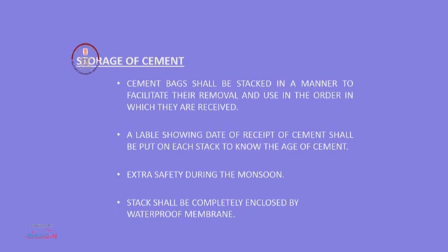To ensure this, we can put a label on the stack saying on this date this cement has come, on this date that cement has come, so that by seeing the date we can monitor that this cement is more than 1 month old, and we have to use it first. So likewise we can provide labels.